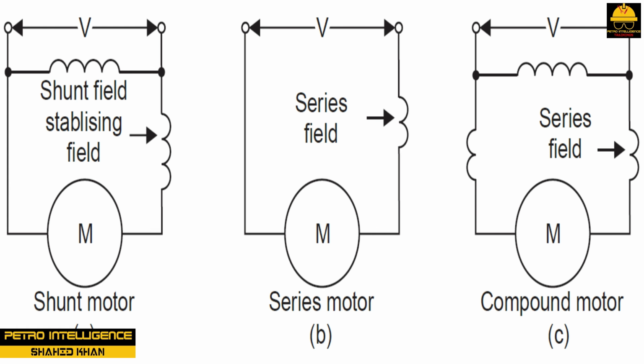Shunt motors are connected in parallel as current flows through the armature and magnet. Wire wrapped around the field magnet provides the resistance and determines the strength of the current and magnetic field. Shunt motors are characterized by their ability to run at an even speed regardless of load. Compound motors are connected to the armature with two magnets, one in series and the other in parallel. Compound motors have the characteristics of both the series and shunt motors.